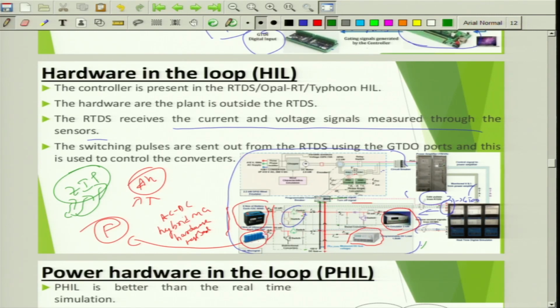These current signals are sensed and passed on to the PI controller present in the RTDS model. Now the control loop during isolated mode works in such a way that it directs the battery and supercapacitor to either charge or discharge, even if there is a change in PV power output or change in load pattern, such that the DC bus voltage remains constant.